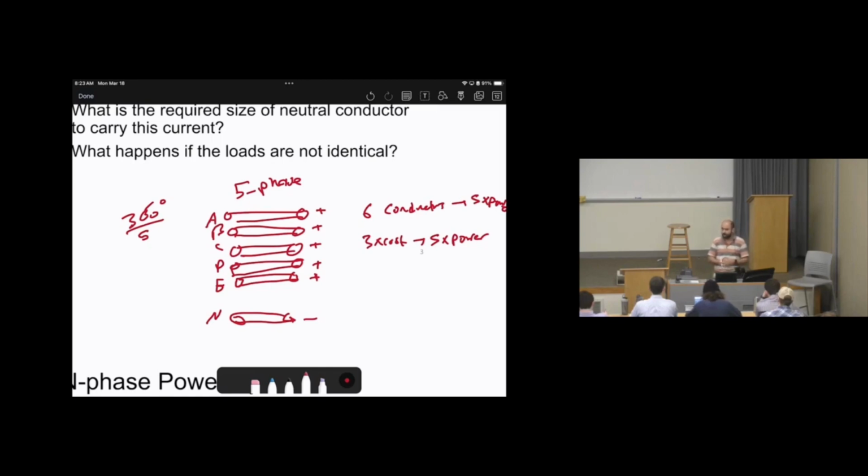So we realized, okay, 5 phase can provide higher power, but in overall cost, 3 phase will be cheaper. So the benefits that we will have from 5 phases will not be significant. And the same thing when we build the transformers: building a transformer based on 5 phases requires a very large size transformer, and this will be a big challenge. So in summary, theoretically, 5 phases is better than 3 phases. But practically, unfortunately, we cannot do that, which is very expensive.